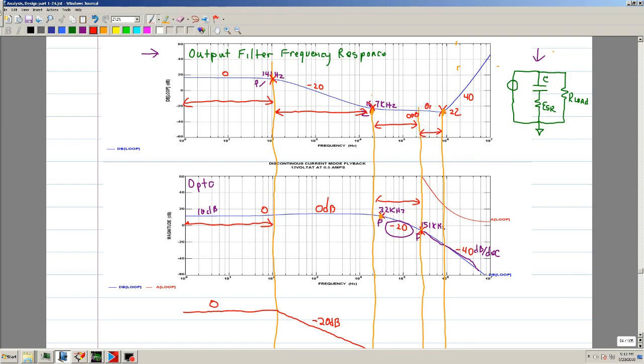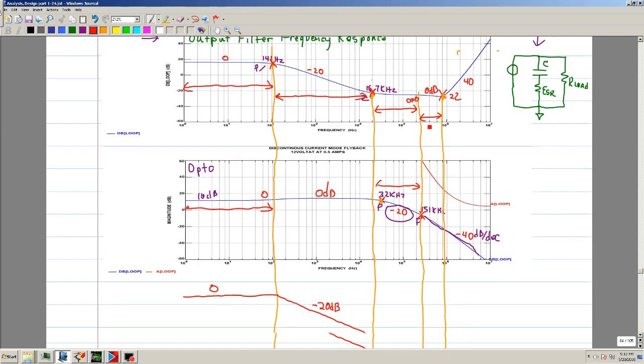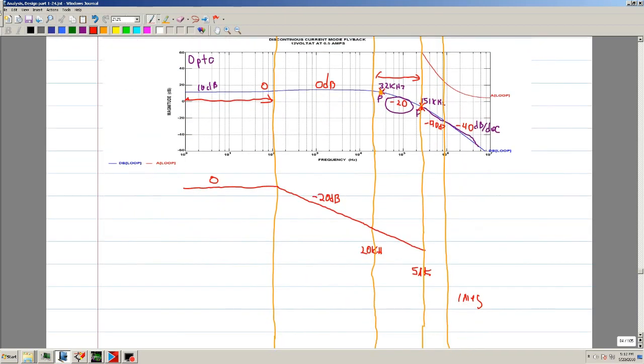So now we're going to add this interval. This is 0 dB. And this here is negative 40 dB. You've noticed the slope of this is steeper than this slope. So 0 plus a negative 40. So you draw this slightly steeper. So this would be negative 20, negative 40.